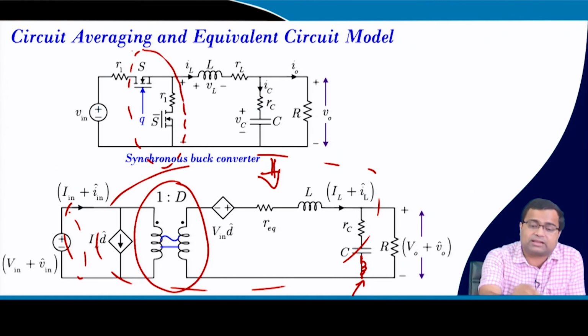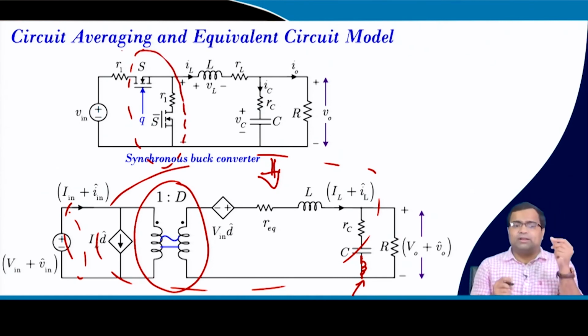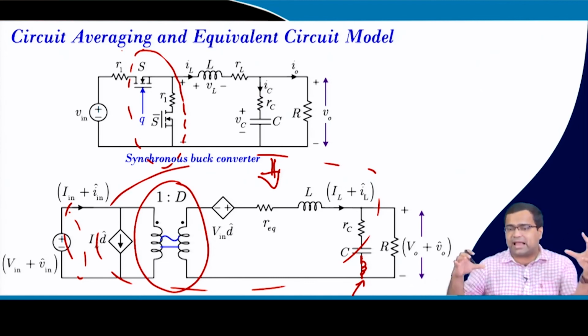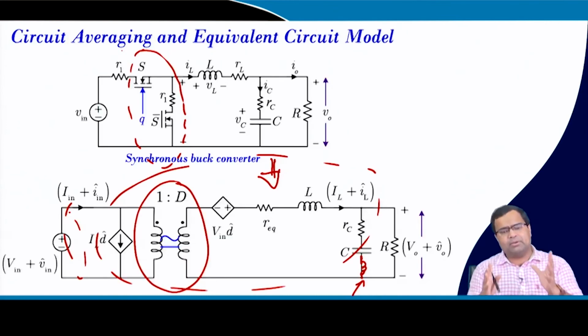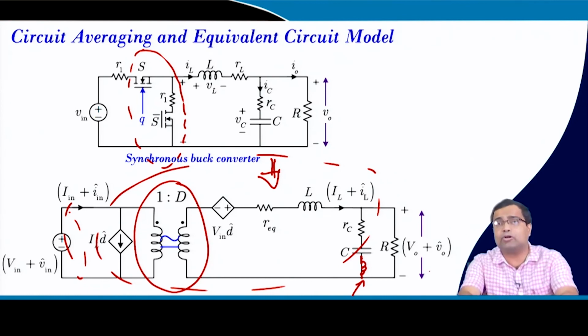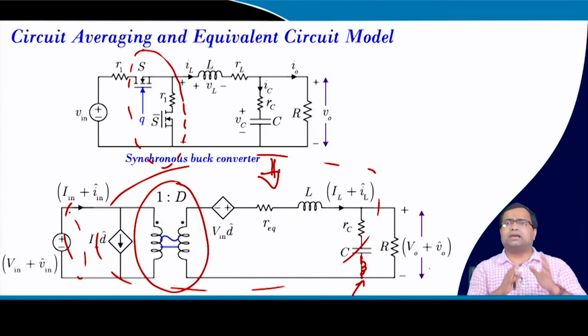If you go to the equivalent circuit model, that means the average switch model, and you satisfy that requirement, then this model is more generic and can accommodate more circuit elements while remaining applicable. And for the same parasitic inductor, capacitor, everything, the transfer function using the circuit averaged model and the state space model are identical.